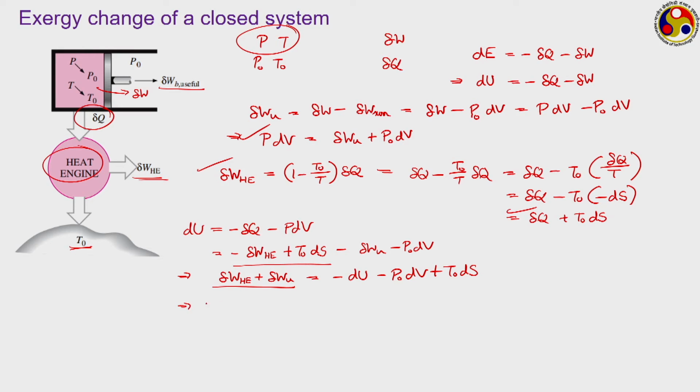So, often referred as the change in the exergy of the system as minus du minus P naught dV plus T naught ds. Actually, this is a reversible work that we could have got from the system during this infinite assembly process, and exergy will be once we integrate this from this initial point to the final point, which is the atmospheric pressure. And so, the exergy of this system is often referred as capital X, quite often used as a symbol for exergy.